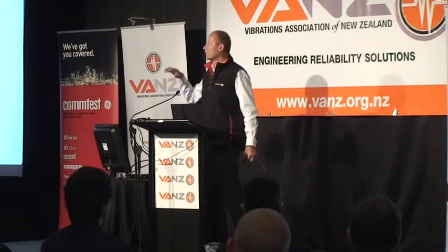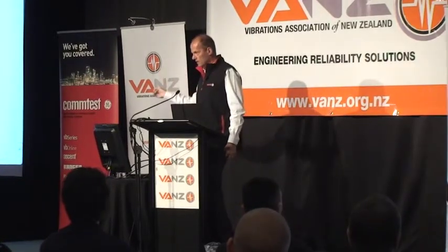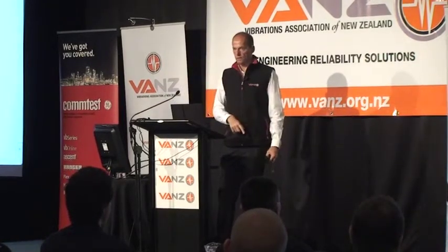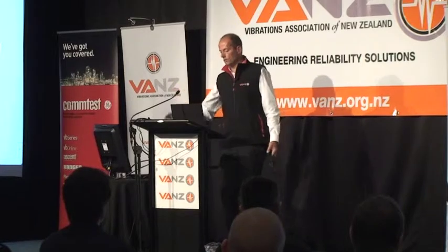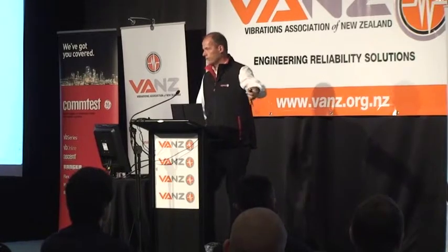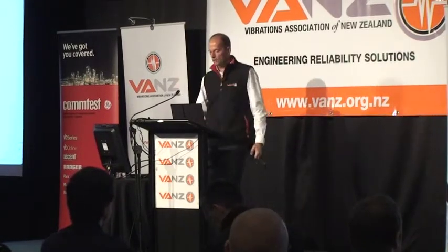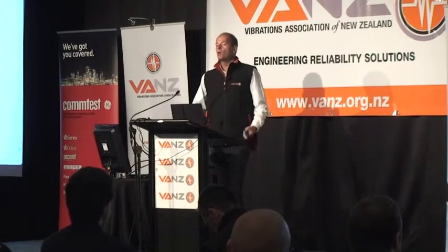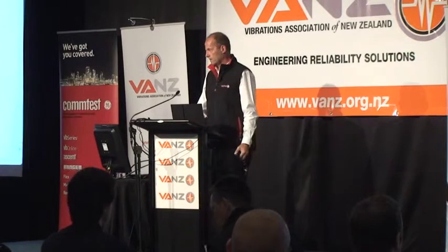I guarantee that if you're not focused on this particular issue, you're putting contaminated lubricant into your machine, thinking it's good and clean. Well, it's not. We're using parts that are already damaged because they've been sitting on the shelf, or they've vibrated on the shelf, or they've been contaminated on the shelf, or whatever. We're not using optimal installation practices, like alignment and the way the bearing's installed and so on.